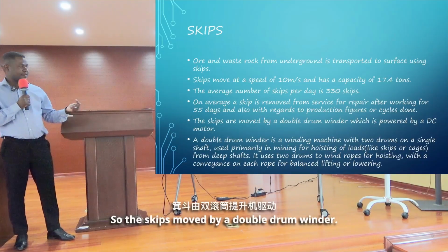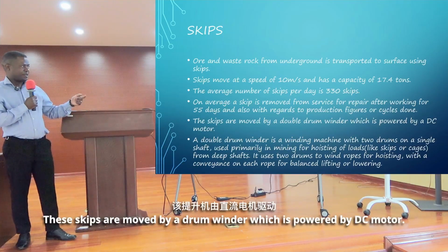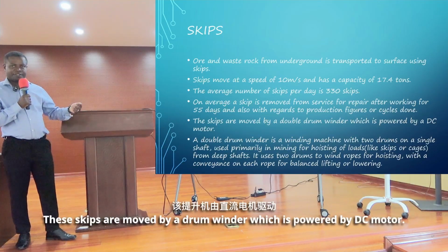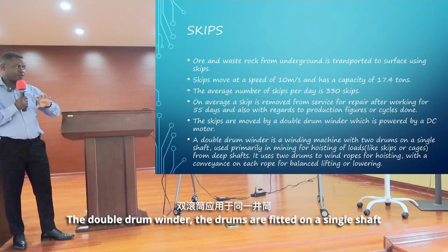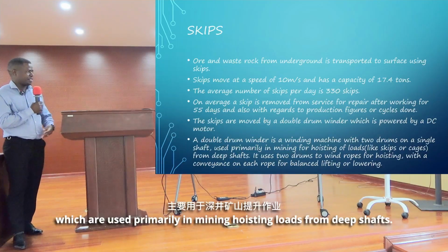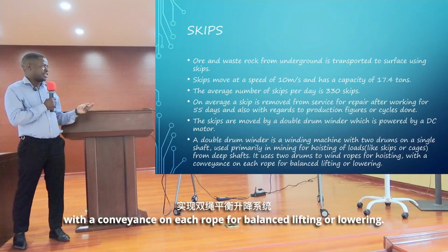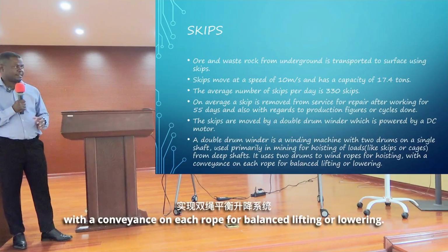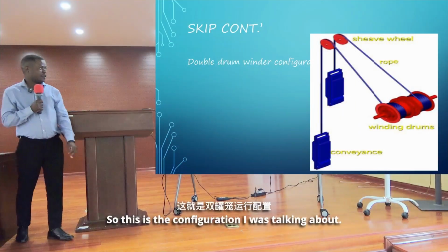So the skips are moved by a double drum winder. These skips are moved by a drum winder which is powered by a DC motor. The double drum winder, the drums are fitted on a single shaft, which are used primarily in mining for hoisting loads from deep shafts. It uses 2 drums to wind ropes for hoisting, with a conveyance on each rope for balanced lifting or lowering. So this is the configuration I was talking about.